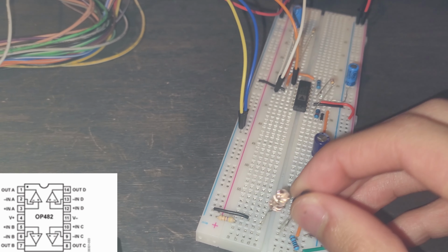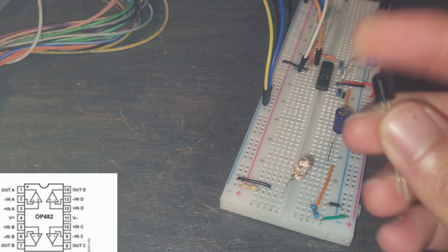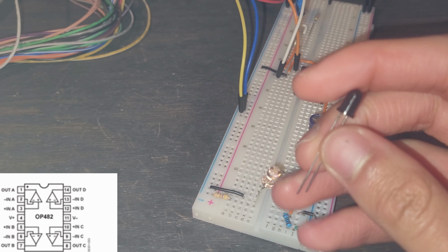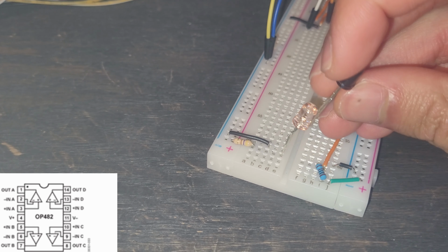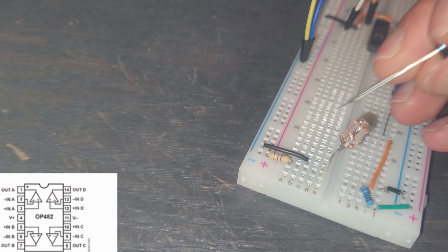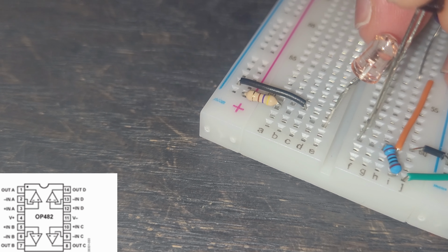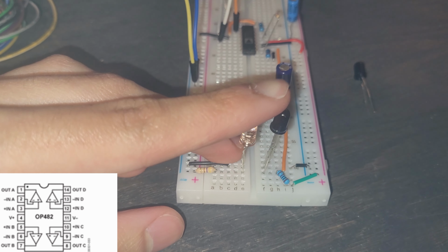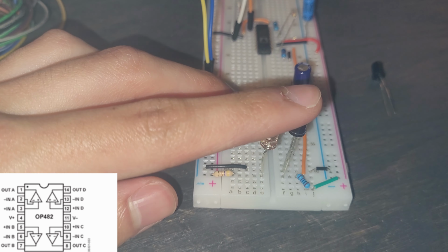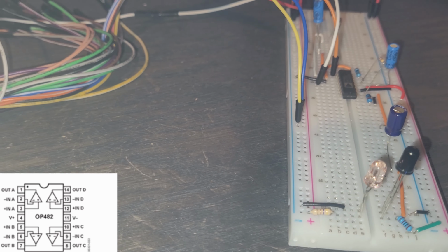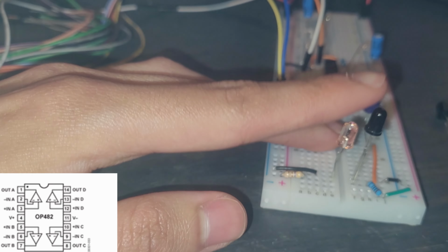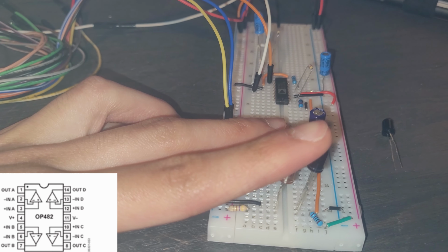Now, if we change this out, make sure you turn off your power supplies when you do this. If I take this one out and put this longer one in, remember we have our anode as the longer one and cathode as the shorter one. Make sure it's in the right columns. So we'll just put it in here like this. And the way I'm going to do it is I'm just going to lay my finger across it like this. That way it gets all of them. So I'm going to turn on the supplies, and then put my finger across just like this.